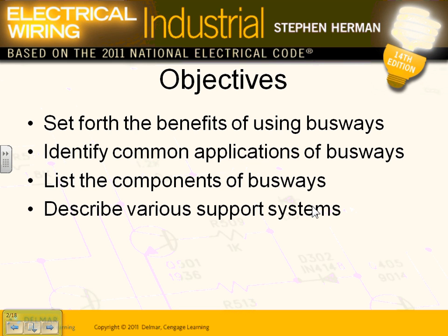What about a really long haul in an office building, a high amount of current over a long haul? You can do it. Yes, it would still be a method of choice. As a matter of fact, we have an example that you guys are going to do, at Boston Scientific. They have a plug-in busway in their hallway, feeding all the rooftop units, a big chunk of amps for the cooling and heating units on the roof. They come from the roof and tie to this busway. That's also a method of choice, absolutely. We'll talk about the support system that we can use.